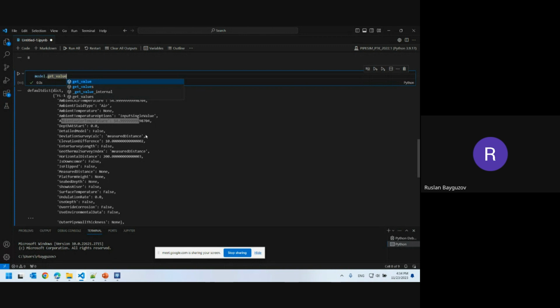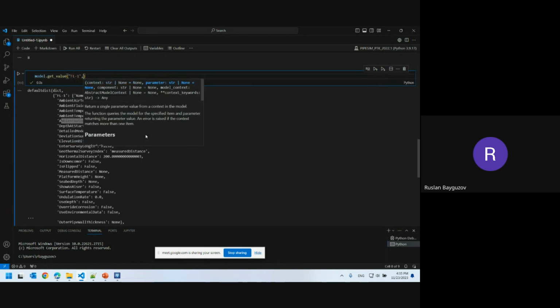You just use the model, set the values, open it through Python Toolkit, get all parameters of the flow line, then change the model slightly in the user interface, save the model again, open another session and compare the two sessions. And you will see what parameter was changed, and then you will know what is responsible for it. It's another option. But in my case, I don't want to do it. I just want to get from the model flow line 1 the same parameter.